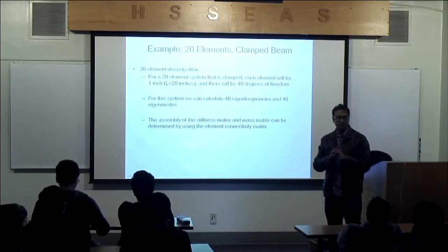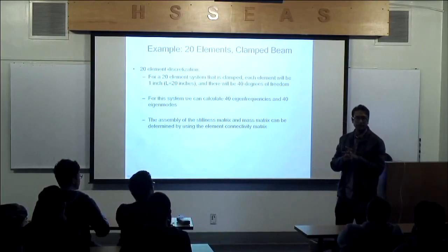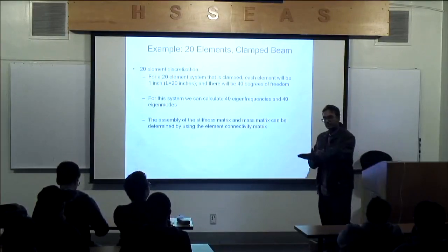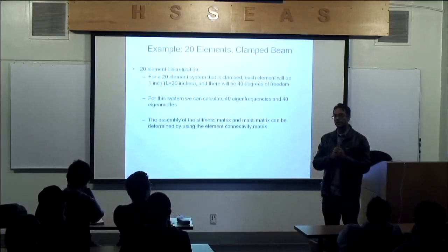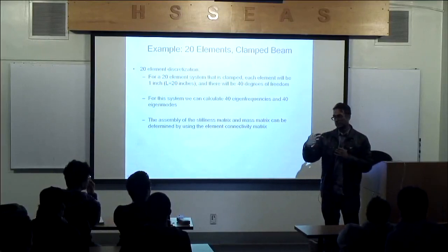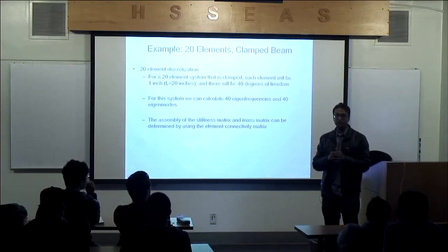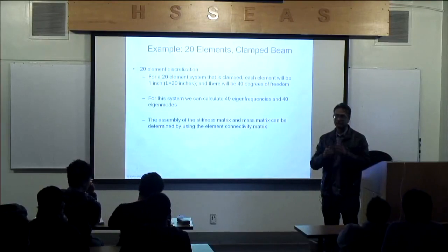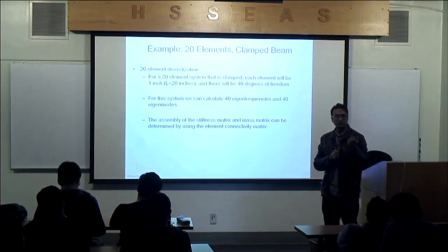MATLAB also has that approach. Now, Abaqus and many other codes have a frequency extraction procedure. They have a way to calculate these frequencies and mode shapes, and they're using something called Lanczos. Lanczos is the frequency procedure that these codes are using to extract the frequencies and mode shapes.